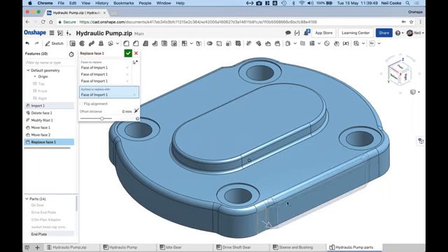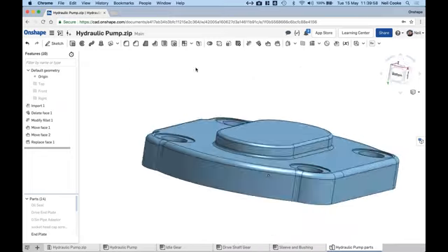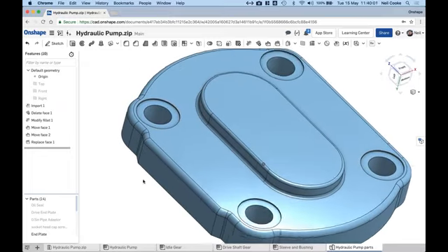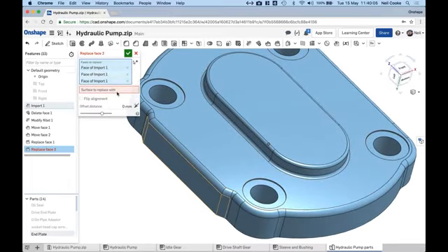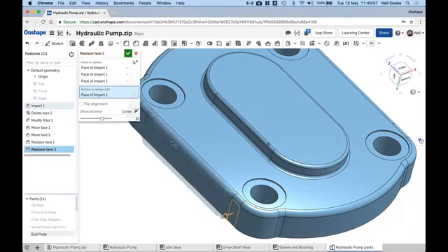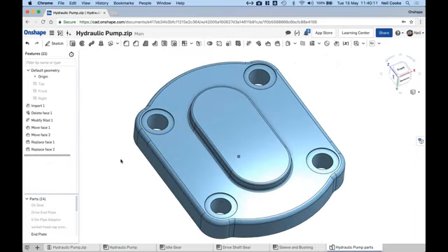Then you can take that, and it's completely removed that. So it means that I've not had to go in there and create a sketch and extrude and reattach the fillet. Everything is created on there to modify that model. And again, very quickly we say, let's get rid of these 3 sides and make it level with this face here. And again, we've modified the geometry fairly significantly from what it was.